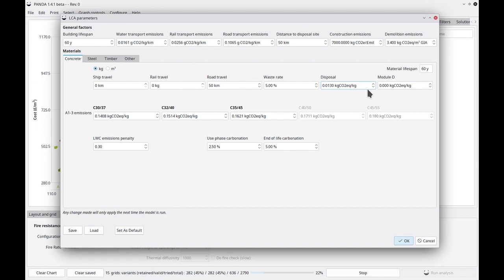These are default recommended distances, but of course you should adapt them to your specific site. You can see all the values, and they can be recalculated, and you can set them as a default. If you have typical values your company uses, you can create a new default and it will open automatically. These are simple text files that you can put in the resource directory, and they will be loaded as appropriate.